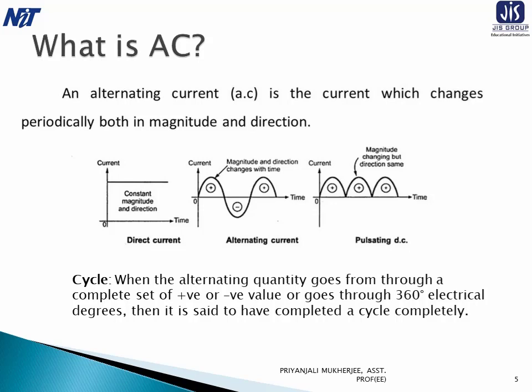The AC induction motor is cheaper in initial cost and maintenance, as it has no commutator, and is more efficient than the DC motor for constant speed. So it is desirable to generate power as alternating current. And the maintenance cost of AC equipment is also lower, and the switchgear for an AC system is simpler than that required in the DC system.